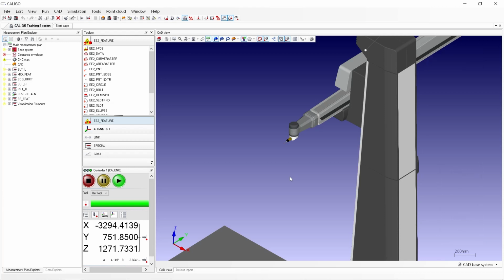Now that we got the controls down for moving our CMM in the simulation environment, we'll go ahead and import the stylus system that we'll use for tactile measurements. This will be a stylus system with a 200mm extension with a RSTP sensor. The first step is to manually drop off the master probe, which is our tool named RefTool.